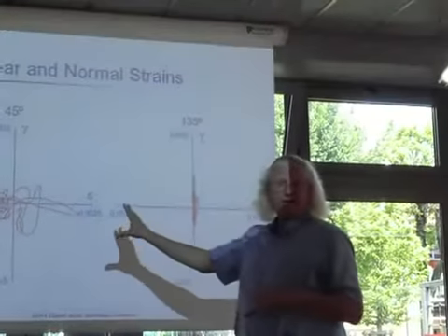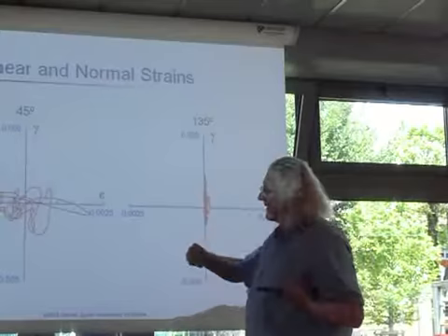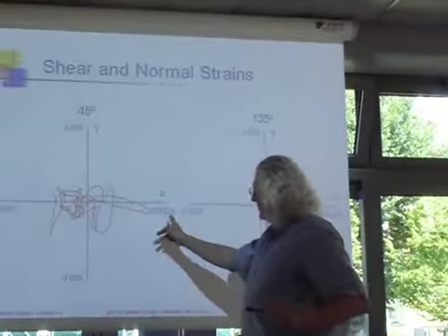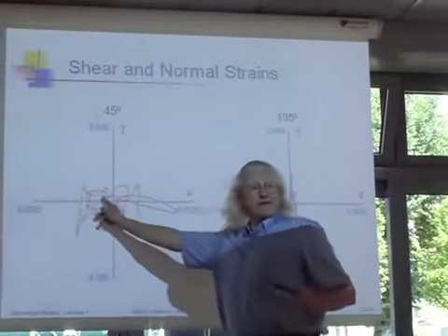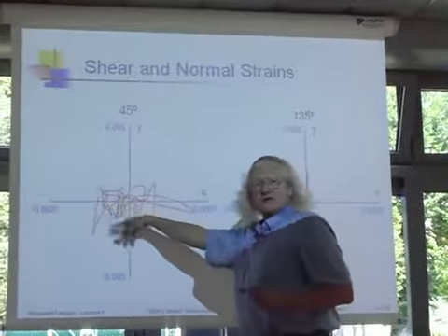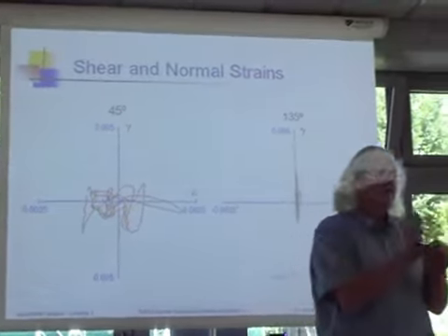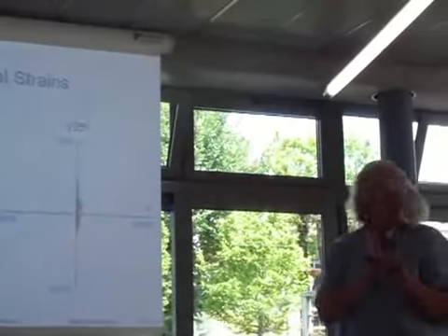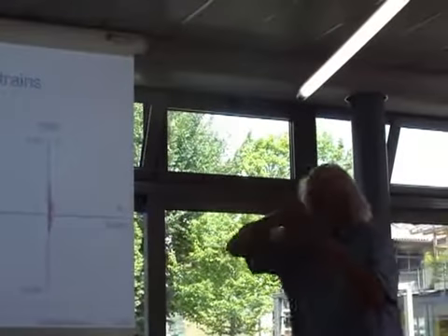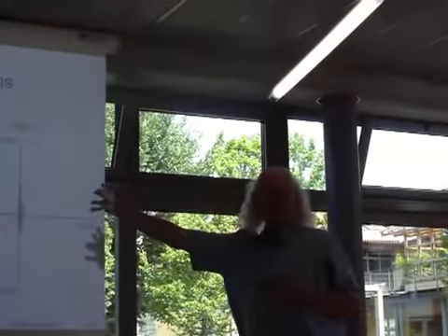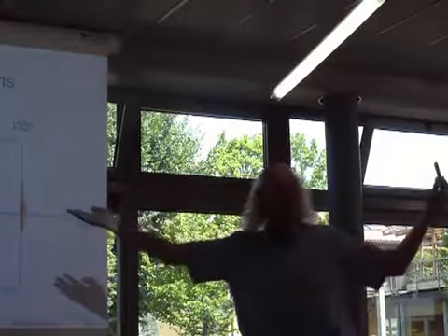At this direction, 45 degrees, all plots at the same scale, you can tell with your eye this must be very damaging. Look, big cycle in tension, and many shear cycles. And if I look at the other plane, almost nothing. So where would you expect this to fail?